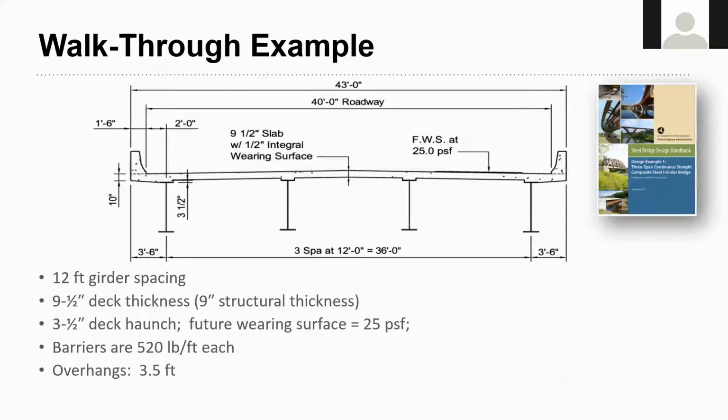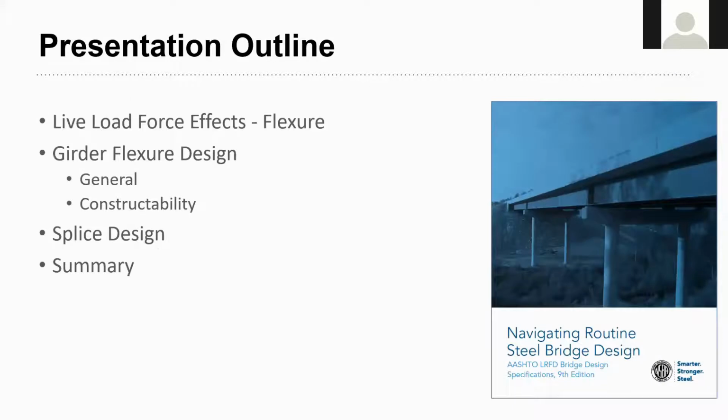And using this guide to help us walk through a couple of the design scenarios that we want to discuss here. What I want to take you through today is how to look at the live load force effects, otherwise known as the live load distribution factors. Girder flexure design, we'll touch on the general and the constructability checks. We'll talk about splice design, and then we'll wrap things up. These 4 topics above the summary are what we're going to focus on today, and how I would use the design guide to help me do or understand the calculations associated with each one of those.